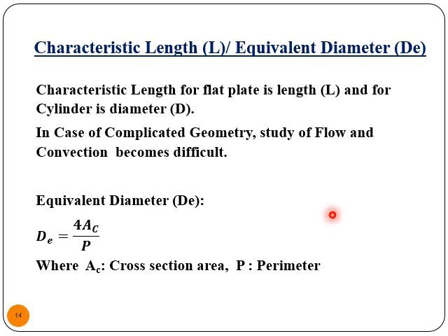If you have a cylinder, and if you have a natural convection, then in that case the diameter of the cylinder which is placed horizontal will be the characteristic length. But if that same cylinder is placed vertical, then the height of the cylinder will be the characteristic length of the cylinder in that case. But if you have forced convection, in which you are forcing fluid over the surface, then the dimension along which the fluid is flowing will be the characteristic length. So you need to remember this.